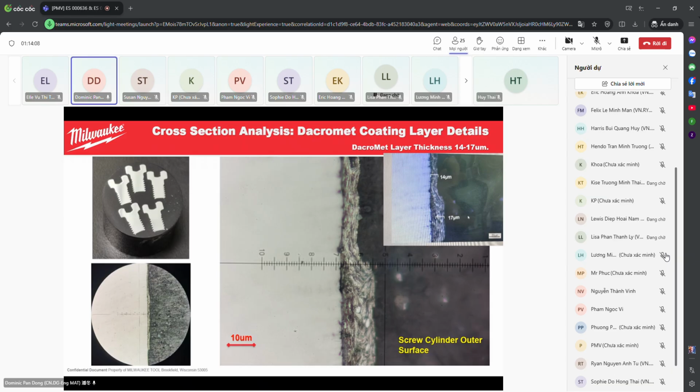And here we go to some samples of different surface coating. Here we can see some samples of dichromatic coating. Dichromatic coating is the most preferred coating process for us for high hardness steel with excellent anti-corrosion performance. In the cross-section of the microstructure, we can see a very uniform, very thin layer with good adhesion, the plating layer on the outside. The thickness is around 17 micron.